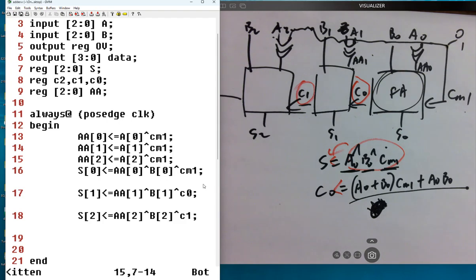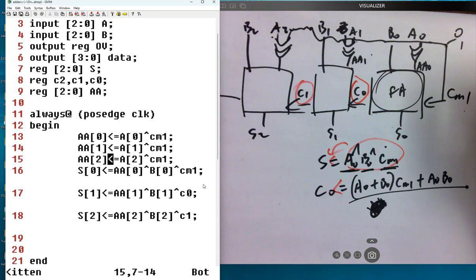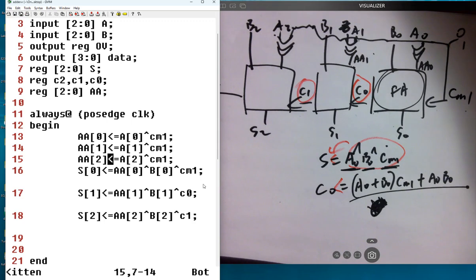So all the signals from the right-hand side will go to the left whenever the clock rising edge arrives. So when the first clock rising edge arrives, you don't have any C0 and C1s, right? They are just zeros. After declaring as register, they are holding the initial 0. So even though it doesn't matter that much, because eventually it will be updated at later clock cycles, it's still better practice to have the signal ready.